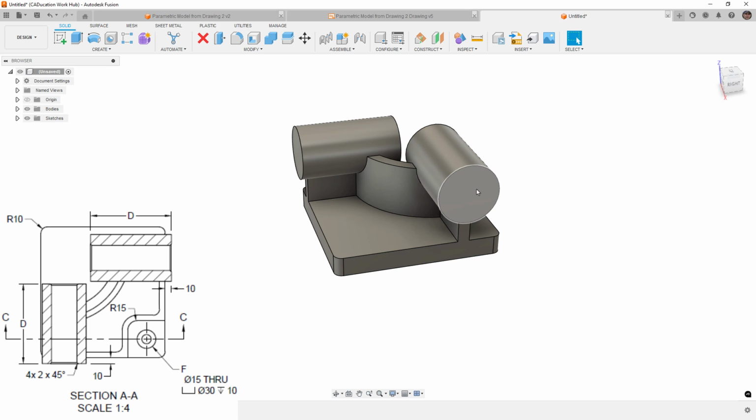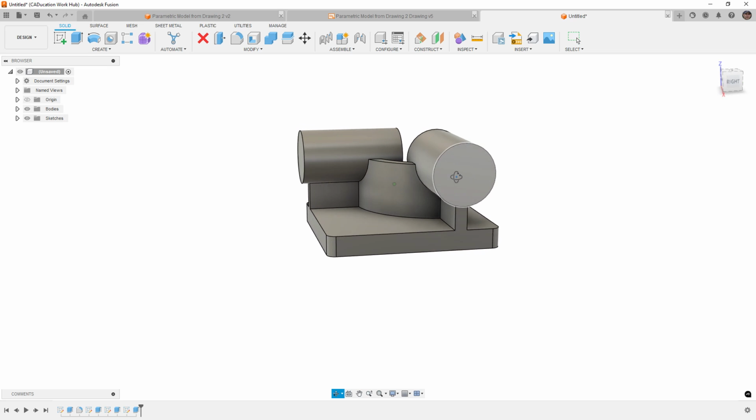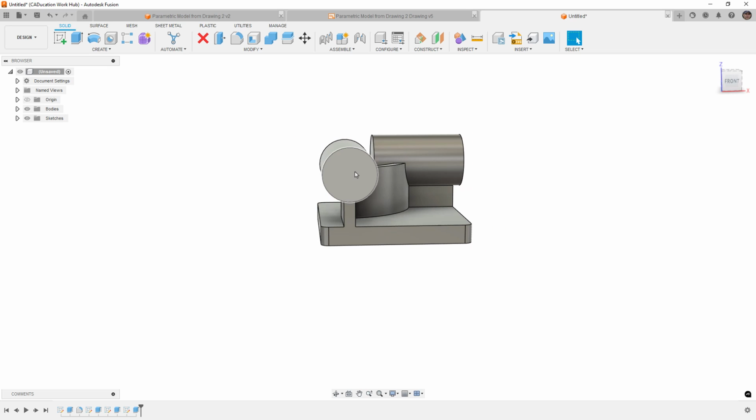And once again, the reason we're not using the inside diameter in this case is because it would complicate the process, because that rib came all the way up to the center. So we couldn't just simply extrude the outside and inside diameter. We would then have to go and remove those sections on the inside. So from my personal preference, it's much easier to add this as a solid and then remove that extra material later. Now let's go ahead and take care of those holes.